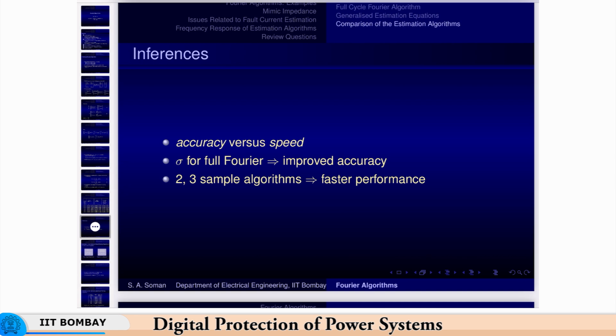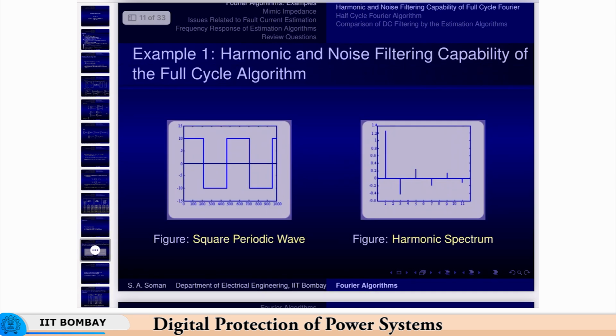You will have to wait for one full cycle, and all the algorithms that we discussed earlier, overcurrent, distance, differential, all that, the computation will have to wait for one full cycle. Okay. And we will see how that is a problem and what can be done to address that. Okay.